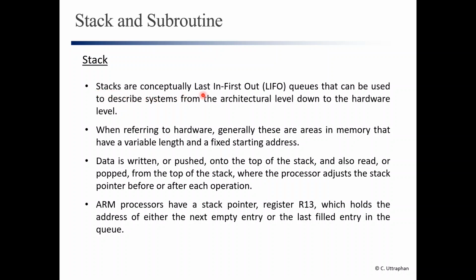Stacks are conceptually last in first out, or in short LIFO, queues that can be used to describe systems from the architectural level down to the hardware level. When referring to hardware, generally these are areas in memory that have a variable length and a fixed starting address. Data is written, or pushed, onto the top of the stack, and also read, or popped, from the top of the stack, where the processor adjusts the stack pointer before or after each operation.